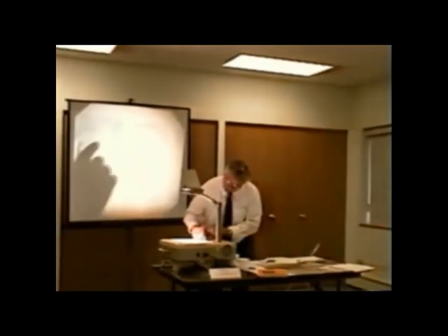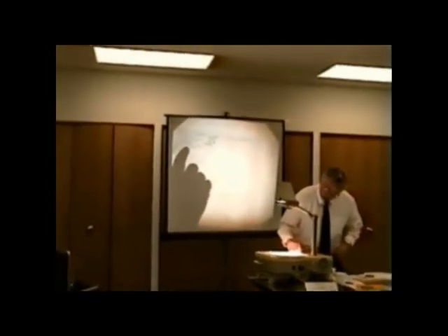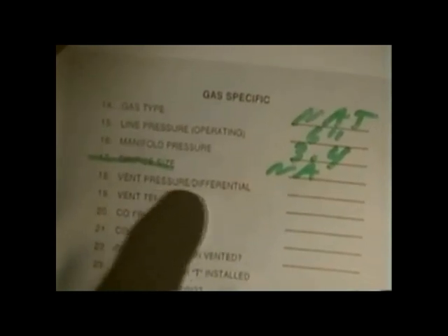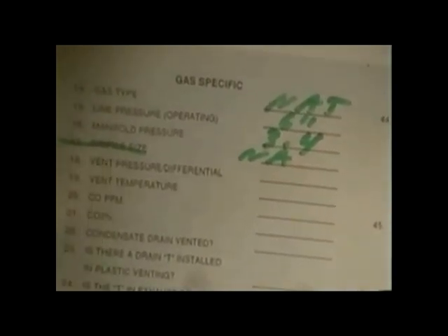Well, let's go on, ladies and gentlemen. Let's go now to vent pressure differential. We use this term because on the older furnaces we had a differential, but really this is the negative pressure from the pressure switches. We're going to ask you for the negative pressure.